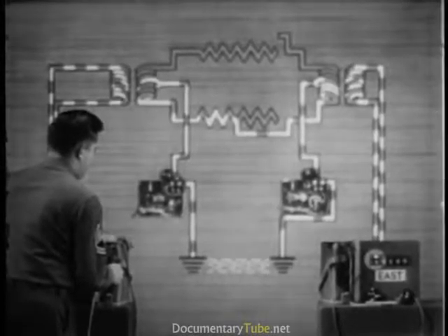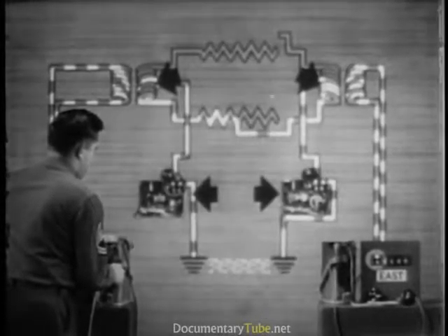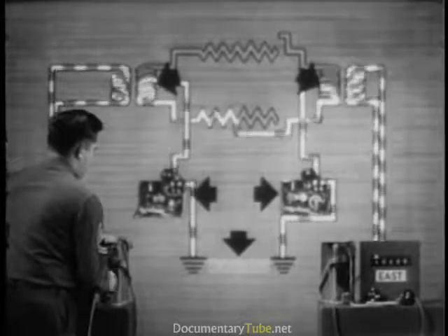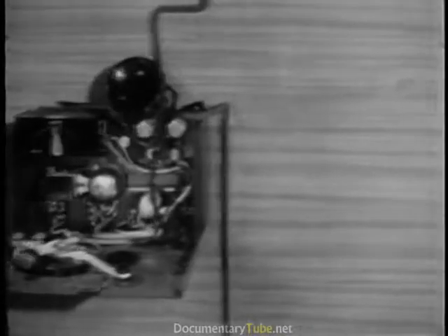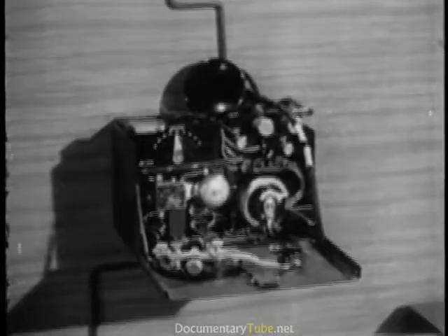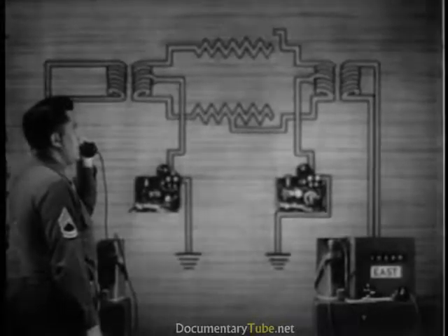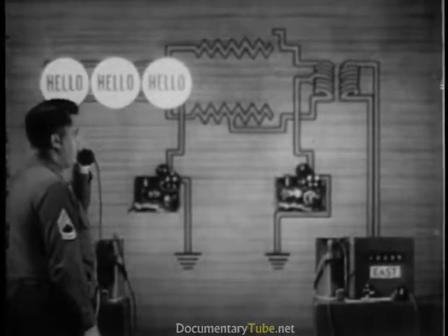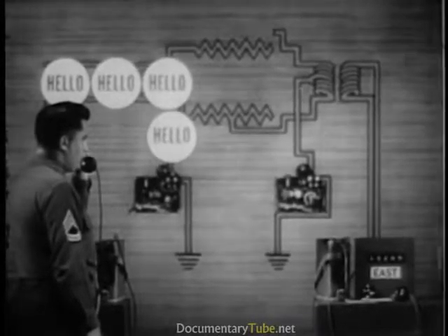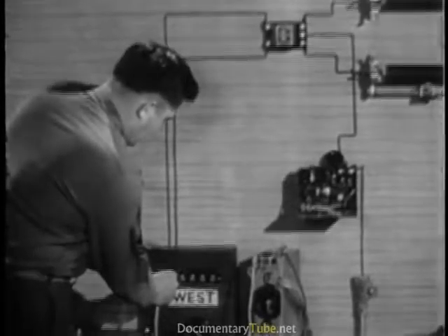The low-frequency ringing current uses the available half winding of each repeating coil, the telegraph sets, and the earth for its path. The ringing signal gets through, and this time it is strong enough to make the telegraph relays chatter and will cause audible interference in both telegraph sets. The higher frequency voice currents, however, are choked down by the telegraph sets to too small a value for an audible signal. Since conversation is impossible, the telephone channel is useless until the break is repaired.